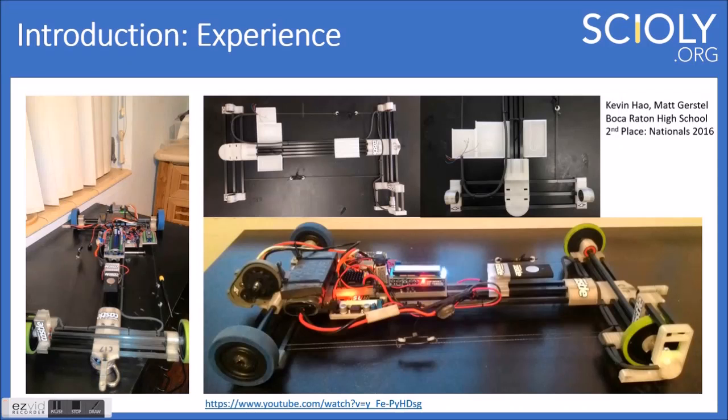We have a third Arduino that was used as the master communicator, so both the other two Arduinos were feeding information to it. This one was like the master control center, and it also outputted signals to the ESC to control the brushless motor, as well as taking in information from the rotary encoder and the LCD screen and compiling and processing that information.